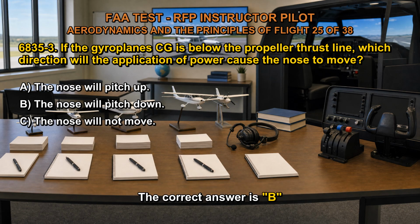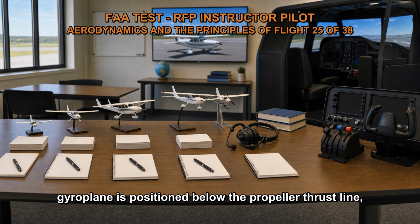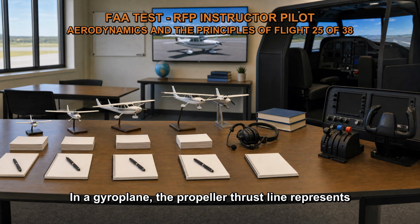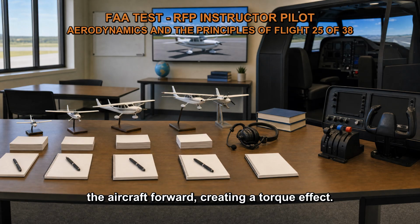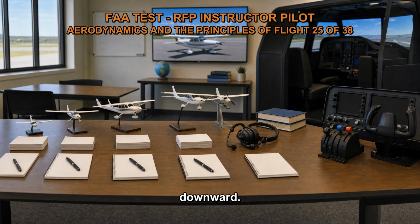The correct answer is B. When the center of gravity, CG, of a gyroplane is positioned below the propeller thrust line, applying power will cause the nose to pitch down. In a gyroplane, the propeller thrust line represents the direction of the force generated by the engine's power. When power is increased, the thrust force pushes the aircraft forward, creating a torque effect. This torque tends to rotate the gyroplane's nose downward.